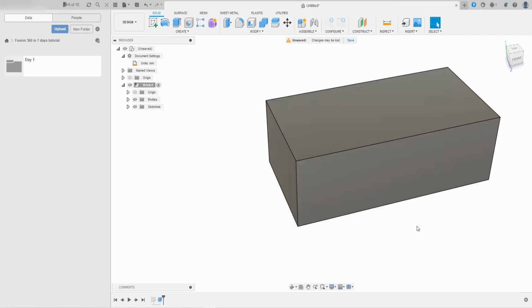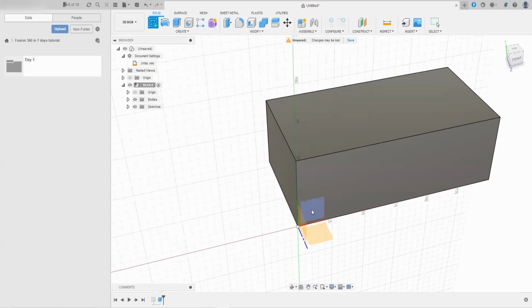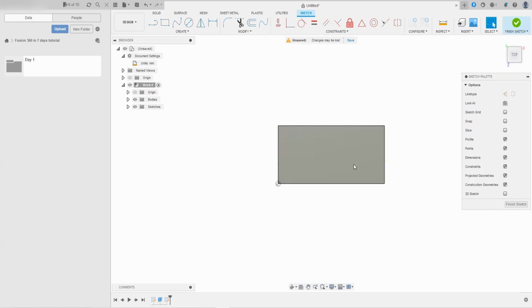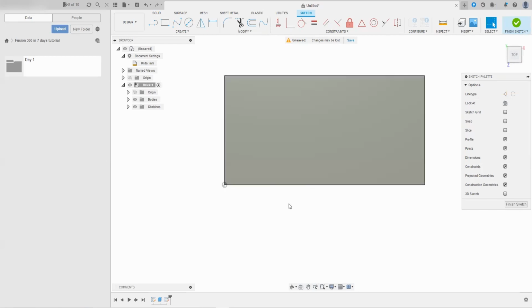Now that we have our 3D solid, let's learn to cut away material to turn this prism into a brick. First, we need to create another sketch. So press on the new sketch button like before, and the origin of the environment appears. However, this time, instead of choosing one of the origin planes, since we have a solid, we can choose one of the solid's faces as the sketching plane. If you hover the mouse over the solid, you can see that the plane is highlighted, and we can click this plane and select it. And as a result, you can see that the environment will turn parallel to the screen like it did last time when we chose the origin plane.